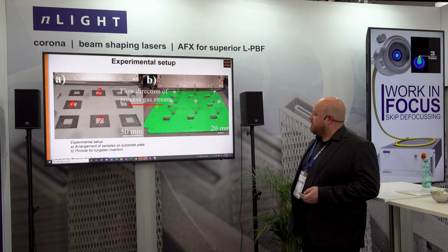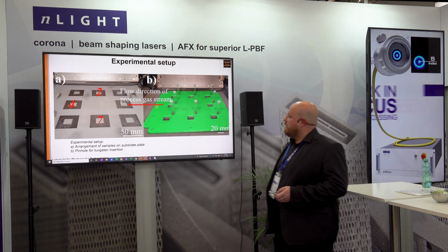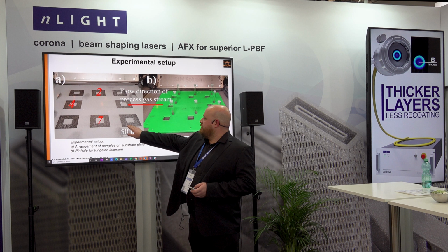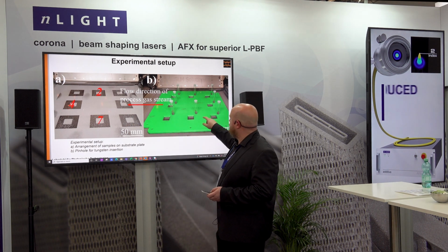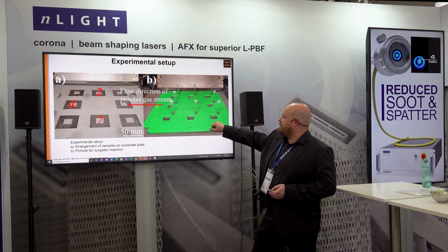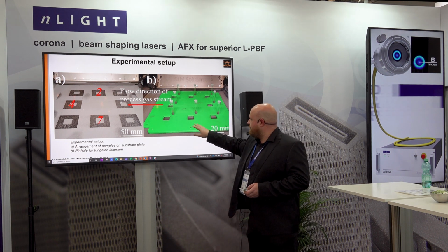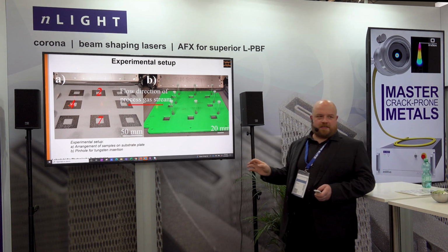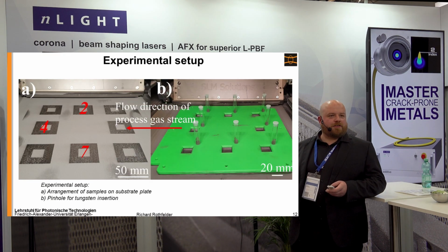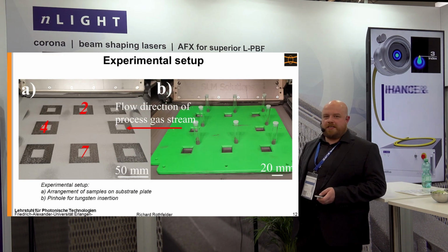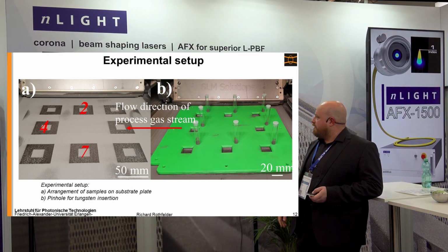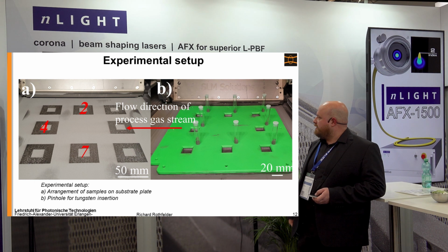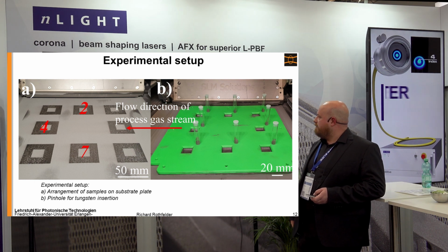Now you see how this looked then in the end. As I told you, we built up to a height of 5 millimeters. Then we placed a pinhole on the surface, removed the Ti64 powder, and placed in every disc cutout a defined mass of tungsten to be sure that it's not just the mass of tungsten which leads to different results here. And we always used 3 grams of tungsten, so we had the repeatability made sure.